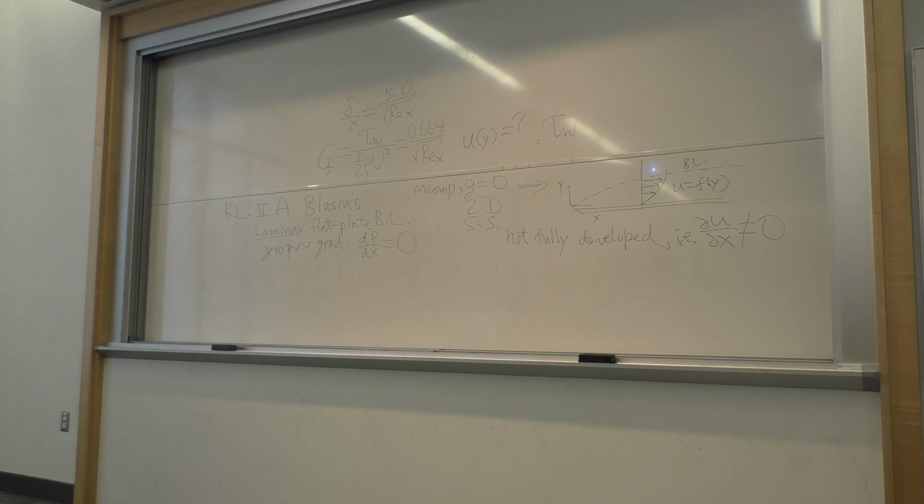Do you want to use Bernoulli? No. Why not? Viscous, there's friction. I cannot touch Bernoulli, or I'll get burned. Right, no Bernoulli. So what else will be needed? Momentum. Momentum, same old, same old. Momentum, except now you have to account for viscous effect. You cannot quite do a control volume analysis like we did before. You need to apply a differential analysis of momentum. That's the Navier-Stokes equation. That's the roadmap.